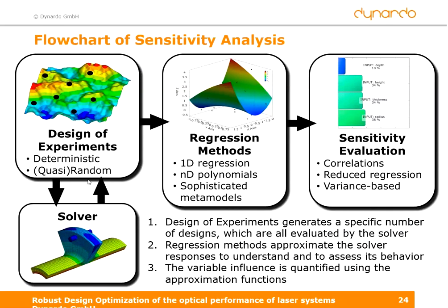So this is a flowchart of the sensitivity analysis. The heart of it is this design of experiments, which means you have distributed your designs in your design space in a particular way, usually homogeneously. Based on this design of experiments, you can now calculate these inputs by the solver, which is here VirtualLab, to get your output.